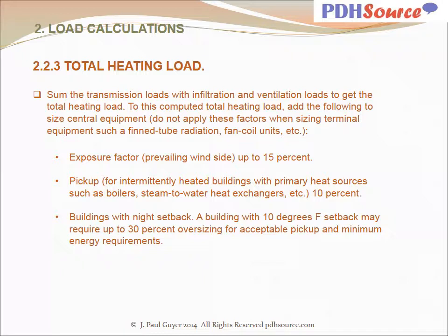This is a recognition of the fact that if you have a building with people coming to work from 8 to 5, when they walk into the building at 8 o'clock in the morning, you will have typically, for energy conservation reasons, turned the heating system off at night. And so at 8 o'clock in the morning, the building is cold, and it takes a while for the building to be warmed up so that the occupants are comfortable.